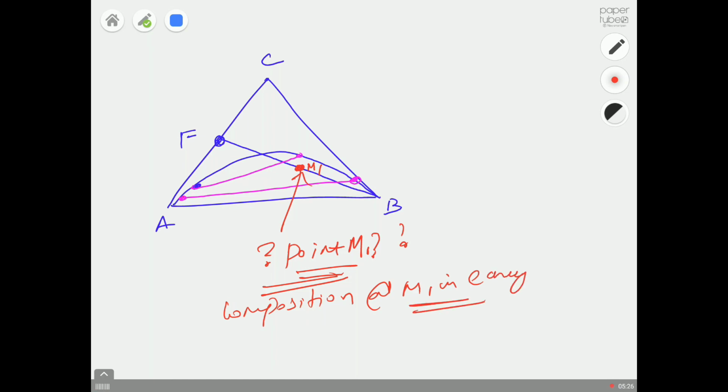And then I will ask you to give the composition of that tie line that cuts through this point, on the extract side and the raffinate side. So you have to draw the correct tie line. I will teach you separately how to get additional tie lines in the image. So something like this, and then you have to tell me the composition of extract here, and then the composition of the raffinate here. So you have to draw this green line by yourself. Yeah, you have to draw the correct tie line.